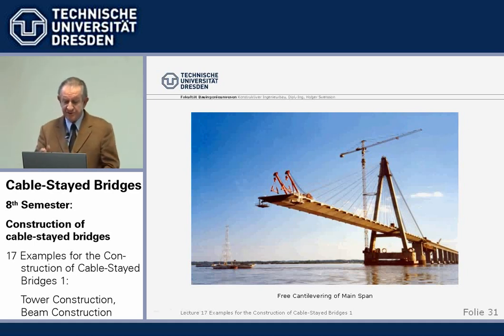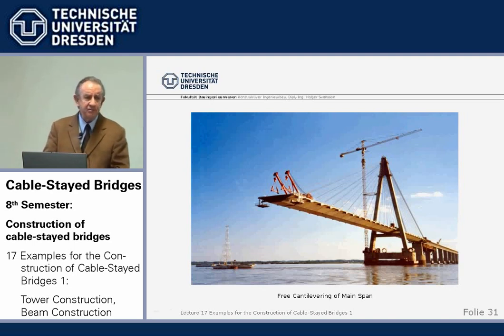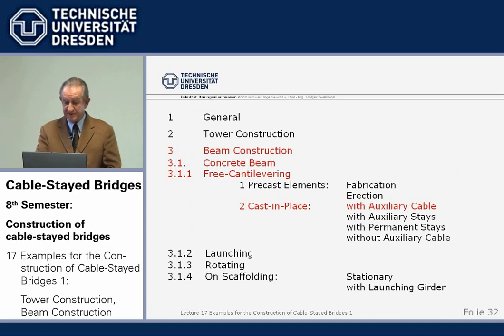All these bridges in Argentina, I think we did 5 of them, have in the range of 300 meters, 350 meter main span. Now, we've dealt with precast element. Advantage, the precast elements are built under controlled conditions, independent of weather and so on, and they can be done very precisely.